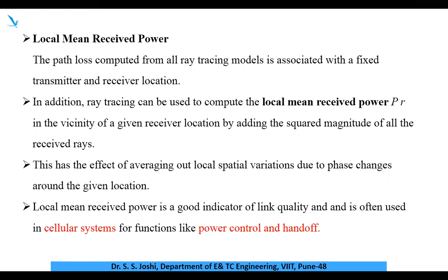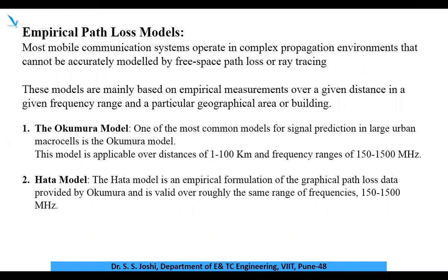to implement this particular wireless communication system. And that's why we are talking about the empirical model. Earlier we discussed the line of sight path, then the 2-ray model, the 10-ray model. So you can say an n-ray model or a generalized multiple ray model. But even with these models, you will not get exact data, because depending upon the environment the data changes. And for that, empirically, we have to use some models.